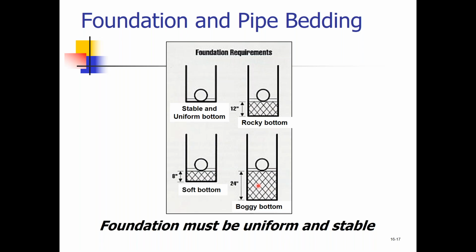The last thing we want to do is spend all the time trenching these areas and putting the pipe in, and then the pipe rolling or settling and not doing what we wanted because we didn't prepare the base and the foundation. You'll remember we talked on Tuesday, if you were here, everything starts with a good foundation. If it's not put on a good foundation, it's not going to last very long. It's going to cost us more money in the long run.